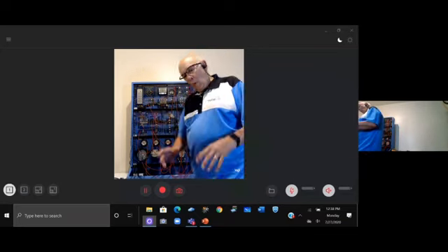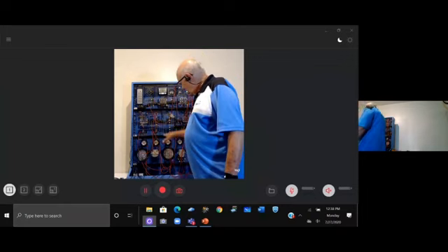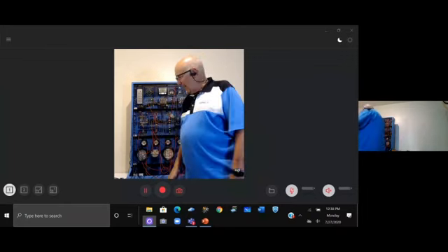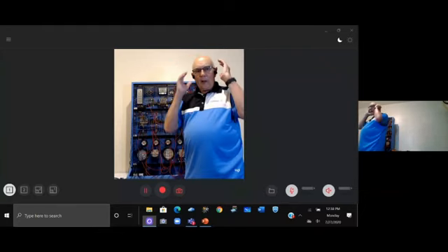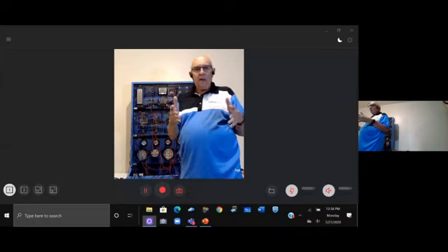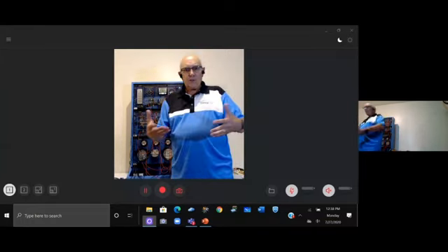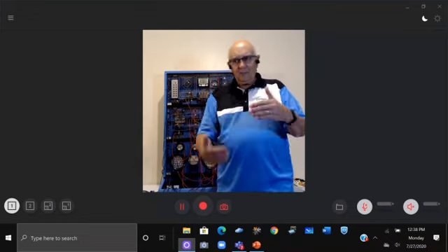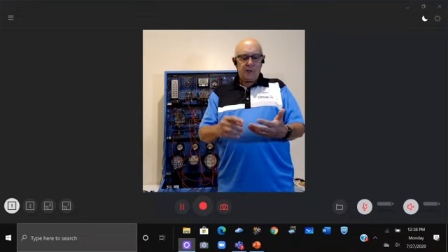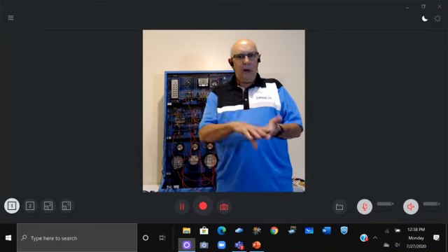Anyway, what I like to do with a student is to say, first of all, prove the lights work. So I have them bring a negative over, bring a positive over, turn the power supply on, and a light works. Okay, so we know the lights work. So what's the next thing? Class, what's the next thing? What does a module need to be able to function? And again, we don't have a lot of back and forth here, but the answer should come back: power and ground and signals. Power and ground and CAN bus.